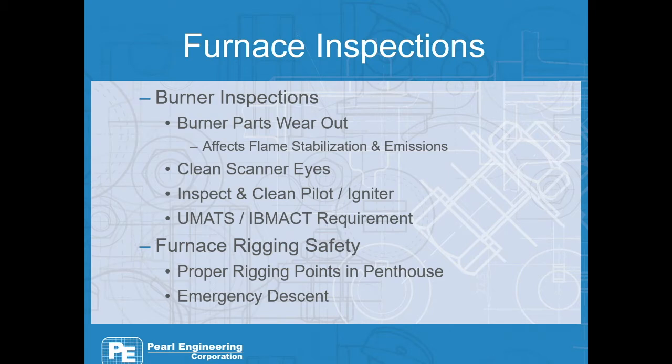Primary area of focus during inspections is usually in the furnace. It gives you a chance to inspect your burners. Burner parts do wear out over time, or can fall off, or your louvers can become loose. This is going to affect your flame stabilization, and it's going to make your NOx and CO control out of whack. It gives you a chance to clean your scanner eyes and inspect your pitots, your pilots, and your igniters, which is important for your startup.